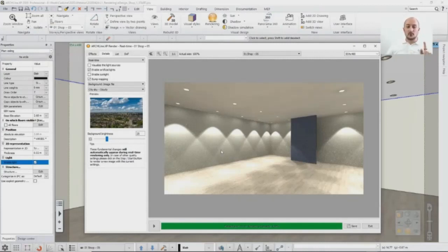This is also important. If you do not have sunlight turned on, most of the time you will have grainier images on lower quality settings. I'm talking about these, and I will show you what those mean. In that case, you can increase the rendering settings, but I will cover that a little bit later. But now we are fine with that. We are not looking for clear images for draft renders. We are looking for reflections, lights, whether they are on, and surfaces themselves.